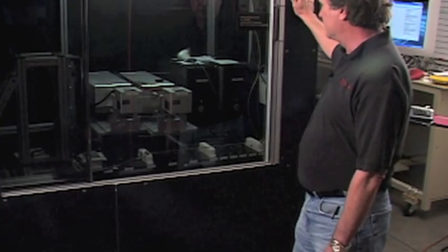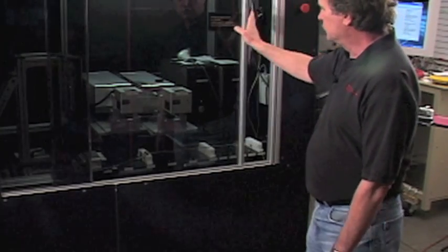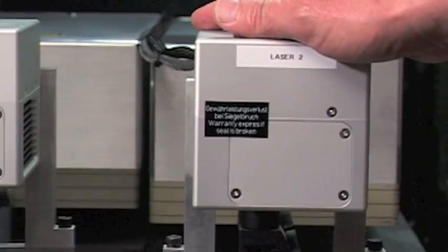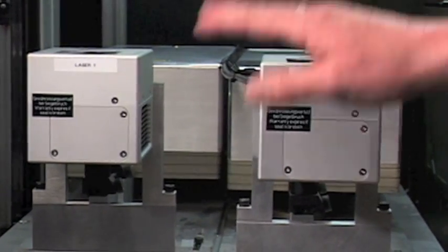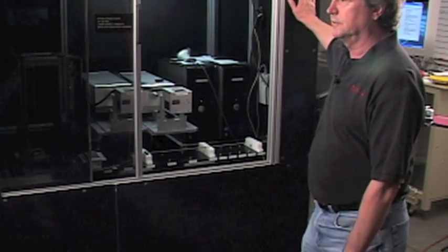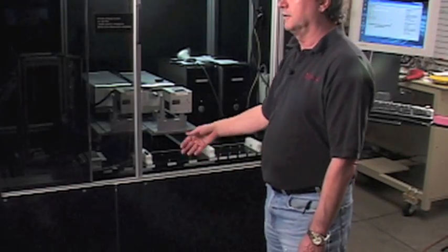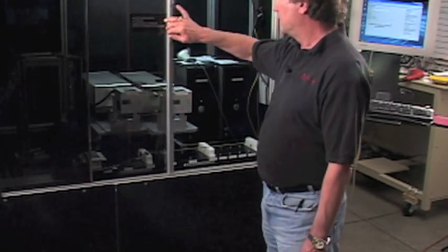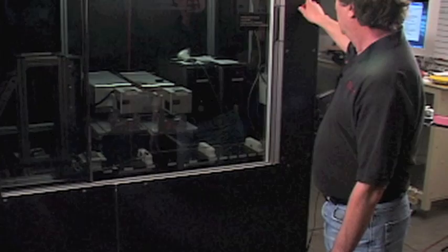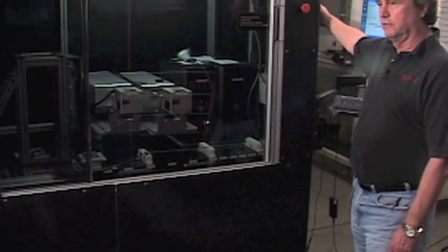If the E-stop is pressed at this point, all motion is stopped, the laser is shut off, the fans are shut off, the computers are shut off, so there's no chance of any danger or injury to the operator. Whatever happened to cause the operator to press the emergency stop, wrong part, not being marked properly, whatever, can be fixed and verified, and the door can be closed, and then you go around and turn on power and recycle the system.